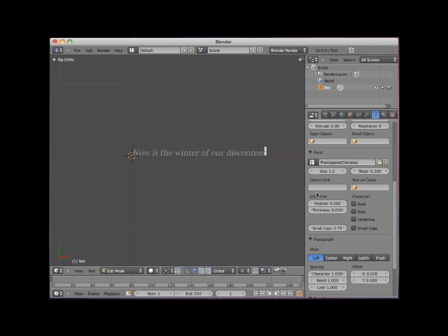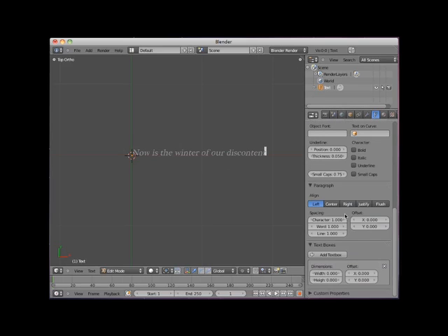By default, Blender text will not word wrap. This is because the default text box, in which the text is placed, has no preset dimensions. I'll scroll down to the text box panel and increase the text box width by making it larger than 0. Note that as I increase this width control, a line appears above the text corresponding to the width control in Blender units.